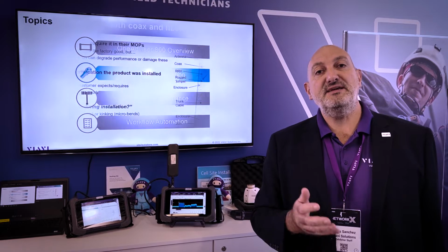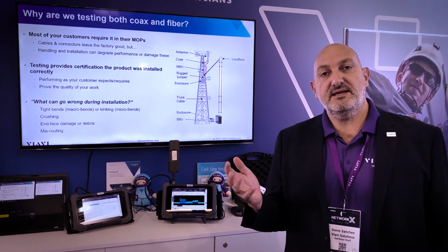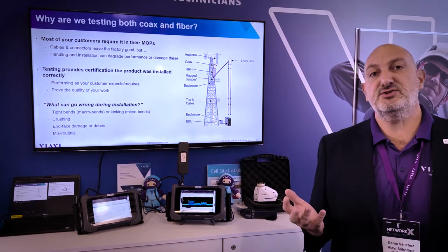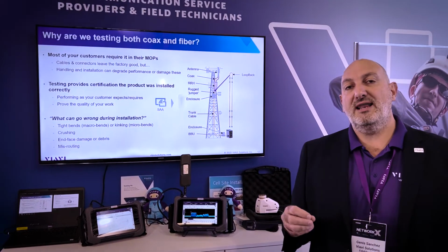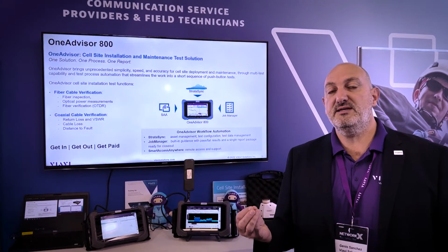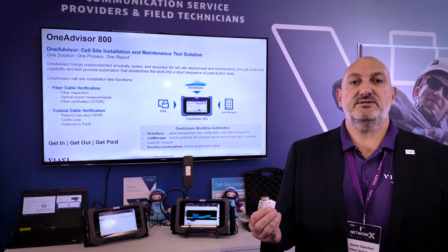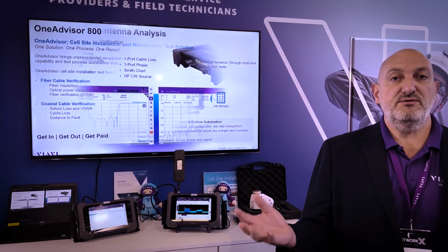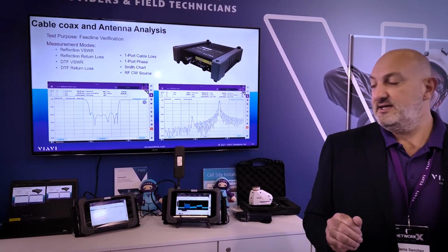So also for the uplink interference, you're able to basically capture the signals with a very powerful antenna, which is the same antenna as the base station. This same methodology also allows us to do PIM detection. So we have the ability to tell you immediately if you have any serious instance of PIM there, and so you can take actions to remove that PIM from that particular site.